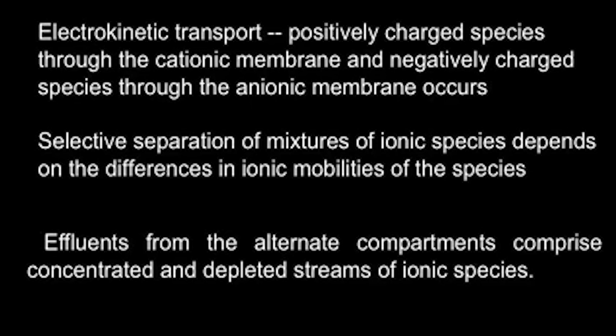So the effluents, that means the liquid that is coming out of alternate compartments, will be concentrated of the ionic species and depleted of ionic species. So you will have concentrated, depleted and so on. So that is the advantage of this particular setup.